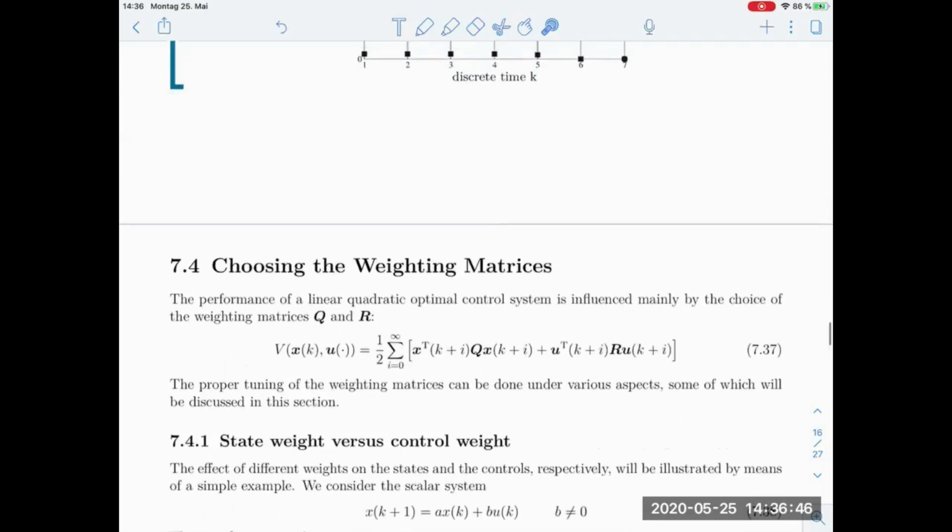In MATLAB, for example, there are a bunch of algorithms and commands to do that. For example, DARE is a command which is an abbreviation for discrete, meaning discrete time, algebraic Riccati equation. And I think you supply, my guess would be, G, H, Q, and R. It's important to actually use the D here. There is ARE as well, but that is the corresponding Riccati equation in the continuous time setting.